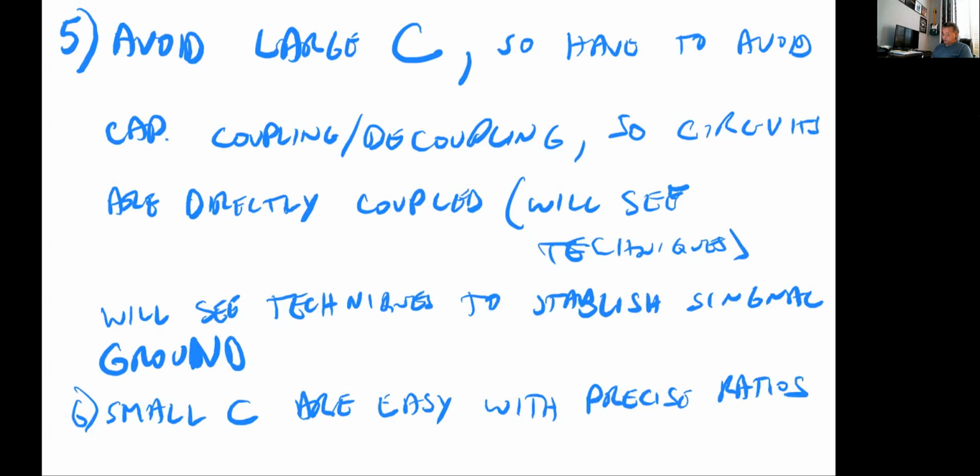And a final point. We're looking at very advanced, very small technologies. So we want the nodes to be small, the transistors to be small, because then we can put more on the same area and fabricate more transistors with the same planar fabrication step. So we like that the transistors are small. However, these are real materials, for example, the oxide. The oxide is the layer of oxide that sits between the channel and the actual gate electrode, the polysilicon. So that's in your transistor.